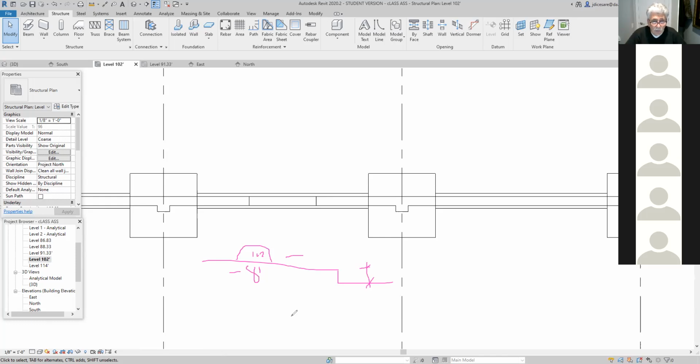So here, what I'm saying is, I'm sorry, I should have drawn this like, the wall comes down here like this, and it comes down here like this. So I want to add what all these values are here. And if you look at EE, you have 8 inches, 1 foot 6 inches, 3 feet, 8 inches, 8 inches, and 8 inches. So that's 2 feet, 5 feet, 6 feet. That's 7 feet 2 inches.